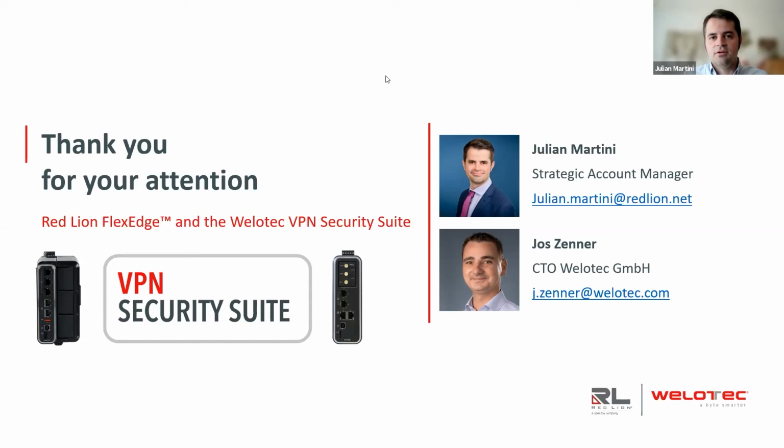When you have response times or communication cycles within 200 milliseconds or slower, then the FlexEdge can be a replacement for your PLC. So this means in some applications we can not only replace 5 devices, but probably 8 or more. Yeah, absolutely, a really lean solution for your machine.